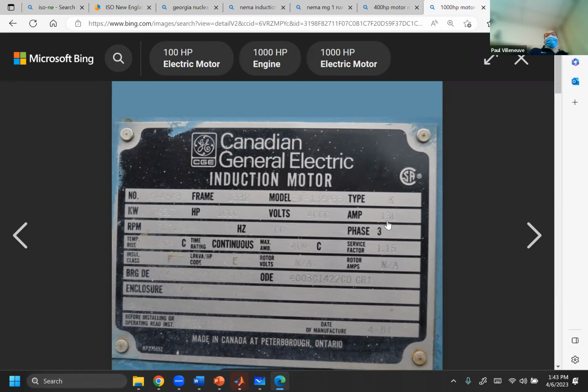Those might be 100 horsepower, but those would either be series wound or a shunt wound DC motor, and they're really good for conveyors. So DC motors are really good for speed control and for locking in position, but I don't ever think you'll come across a DC motor in an industrial application. Yeah, they exist, but they're pretty uncommon. They used to be a lot more common, but more and more because of speed control with drives, you're better off to go with AC because they're so simple.